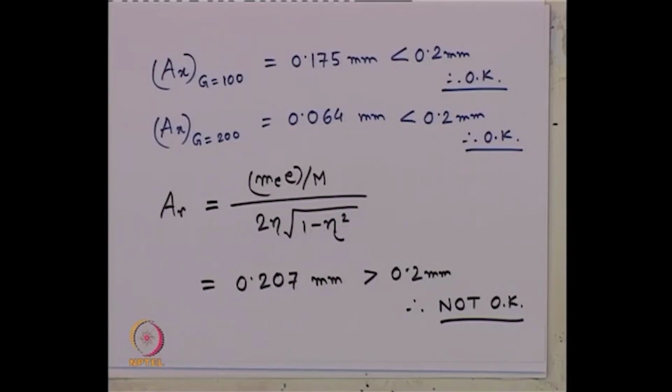Then you are safe and ensured that your machine foundation is never going to exceed the permissible displacement, and it is safe throughout, whether machine is picking up the speed or starting from 0 and then slowly building up the RPM or something like that, but still your machine foundation will remain safe. So, these are the checks needs to be done, and that can be easily done by using the simple mass spring dashpot model, what we had learned in our module 2 also in vibration theory.